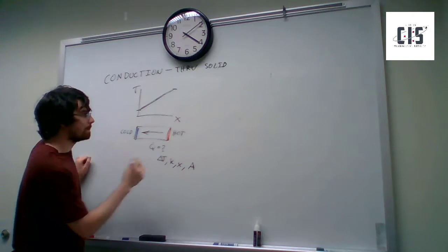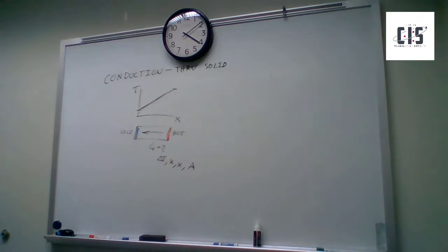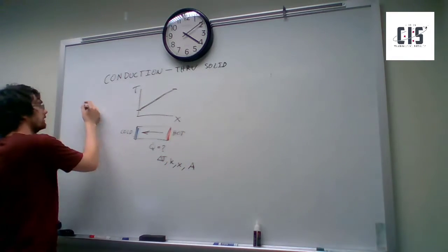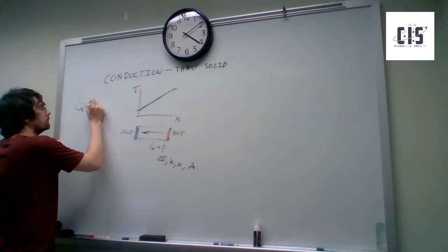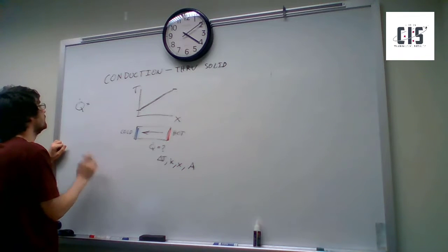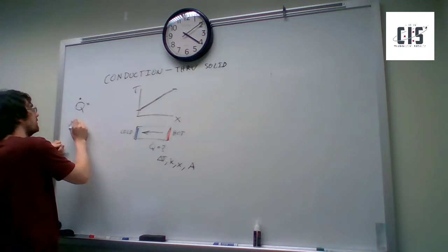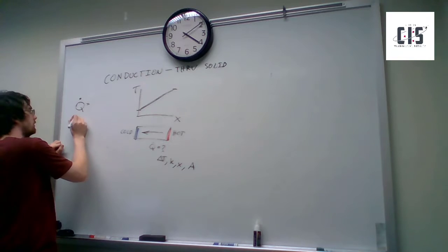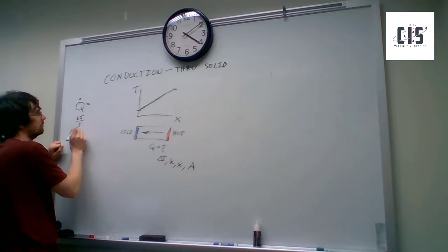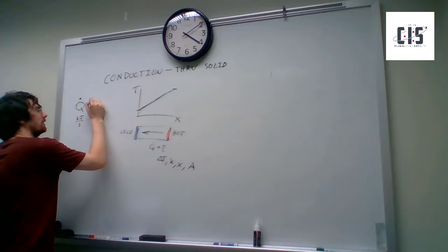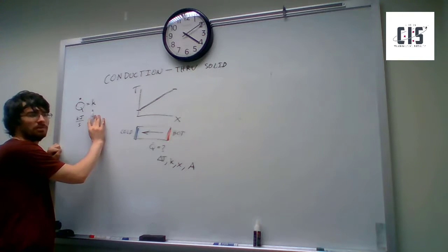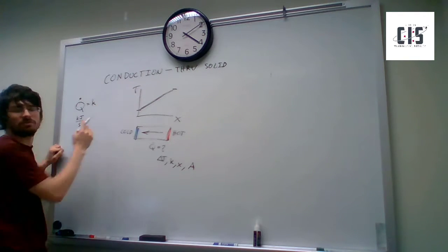Okay. So let's double check my formulas. So Q dot right here. And Q dot is heat transfer rate. Okay. So how fast heat is moving. Right underneath that. Yeah. So that's what the dot means, the rate. I'll just say kilojoules per second. How's that? So that's rate. So it's equal to a constant based on the material. The constant technically depends on temperature, but usually you assume it's constant just for simplicity.